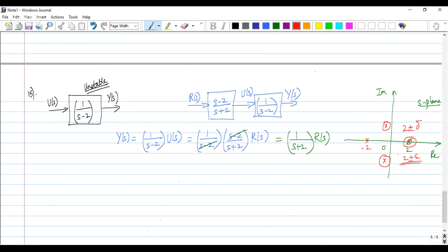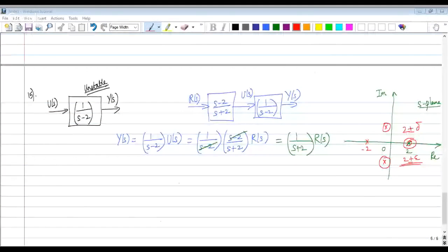So when we go closer and closer to the imaginary axis, which is the boundary of stability, there may always be some perturbations, parametric variations in the system, which can slightly change the location of these poles. Sometimes they may even cross over to the right half plane. Under such situations, if we just use pole zero cancellations, we are going to be off, right? The zero which we designed is not exactly going to cancel the pole, and then the system may become unstable or erratic, right? So that's something which we want to avoid. Okay.